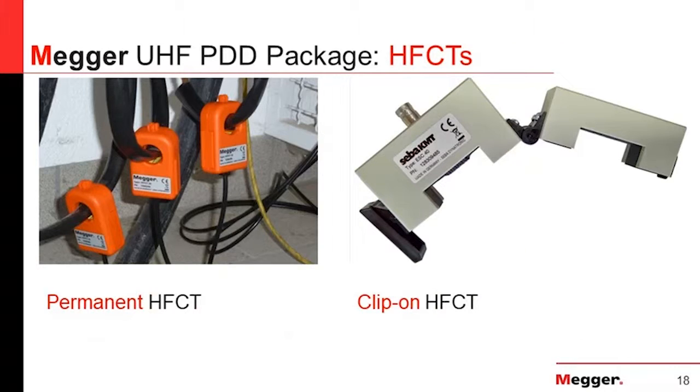Then we have a range of HFCTs, either permanent HFCTs or clip-on HFCTs. Depending on the application, those HFCTs can be installed and used for partial discharge detection. But HFCTs work in the VHF frequency range, so not UHF.